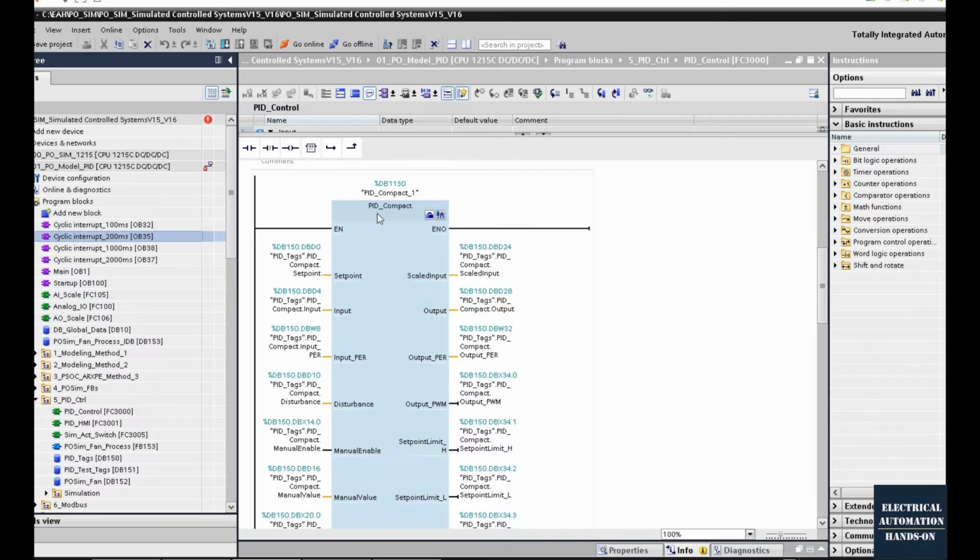That's because our model and our algorithm take care of the sample time. However, our processor, our PLC, only takes care of the cycle time of the interrupt. It doesn't care about your actual process value, response time, and response behavior. So we will shrink the interrupt cycle only. That is the first method.